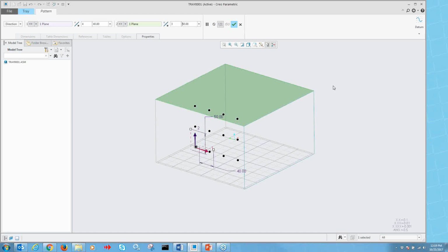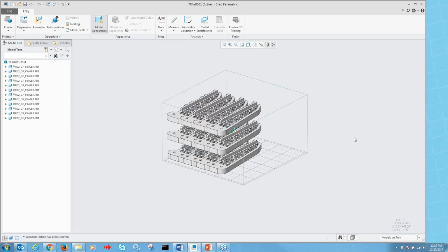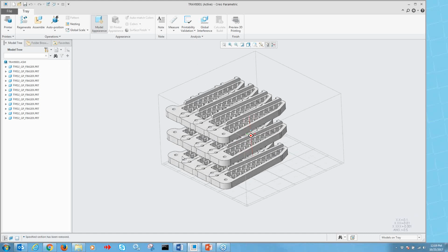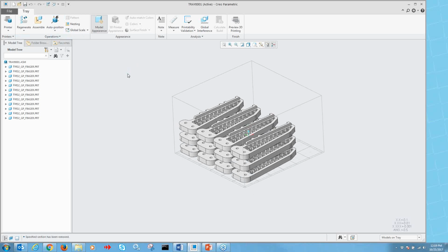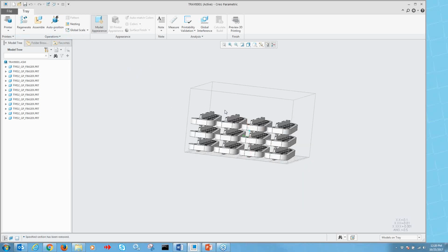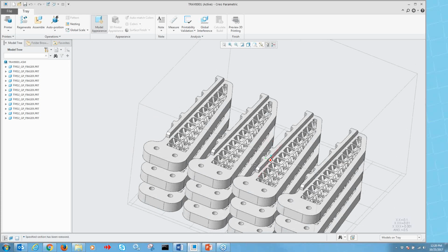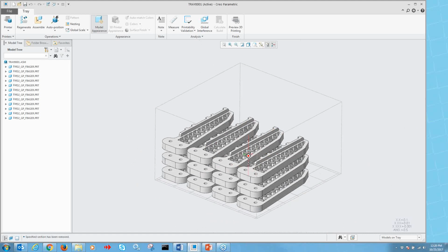All right. So I have all that done here. Let's go ahead and check this off. And again, our parts are in there, but again, they're kind of overlaying one another. Not going to work out too well, so let's just use the software here to take care of that. We're going to pick the auto position and then arrange on the tray. Now you can see here, we have the parts evenly spaced out, ready to go, and not interfering with one another. Optimized design here, so we've got the printed parts stacked up nicely in this process.